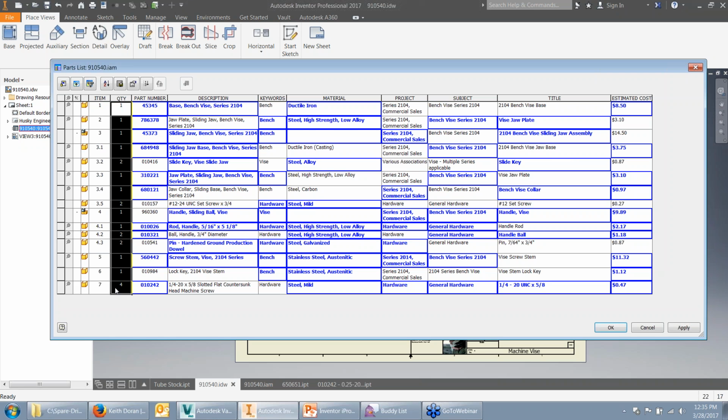That's the only time I would foresee a need to actually set up a static override in the parts list. Give them a little bit of a pad. Give them a couple of extra screws or washers or things like that. That's easily done. Change the quantity from whatever is being calculated, from 4 to maybe 6.